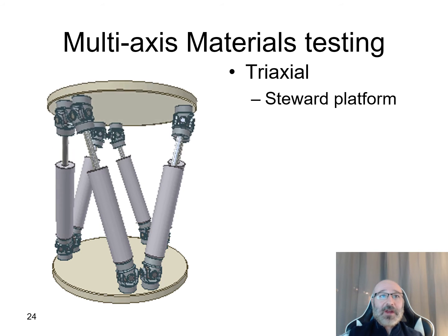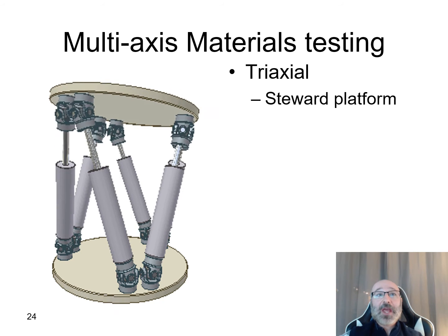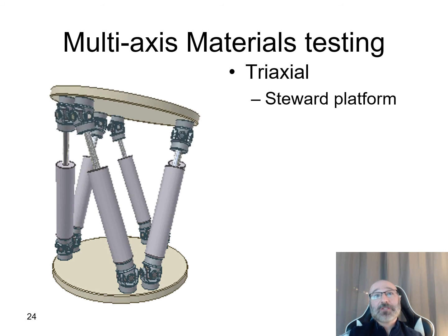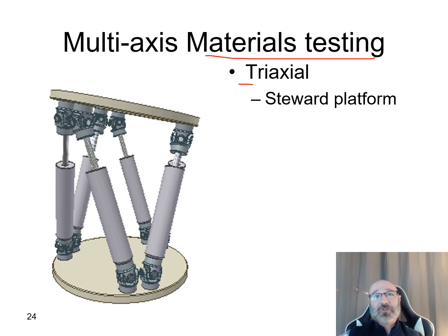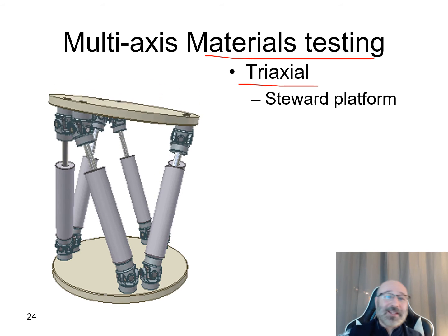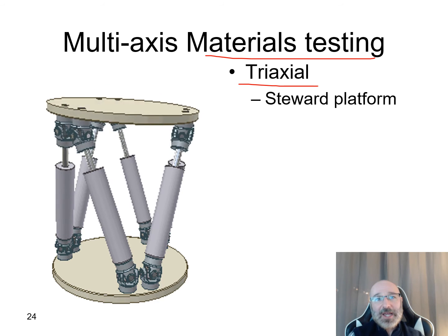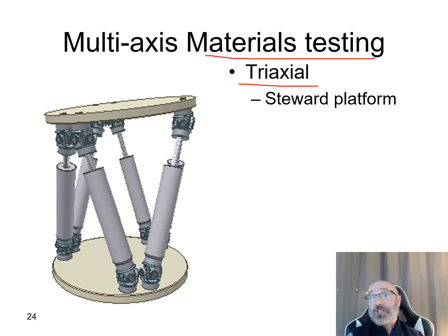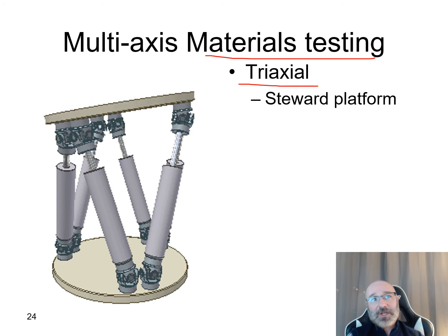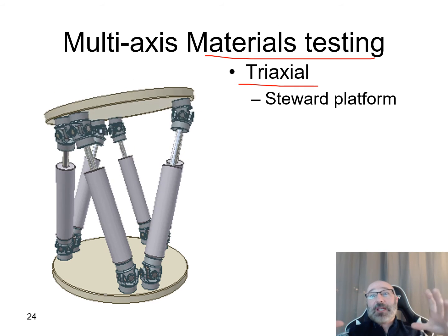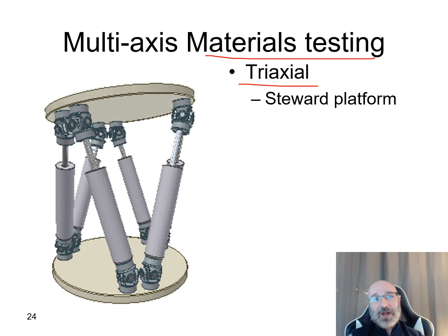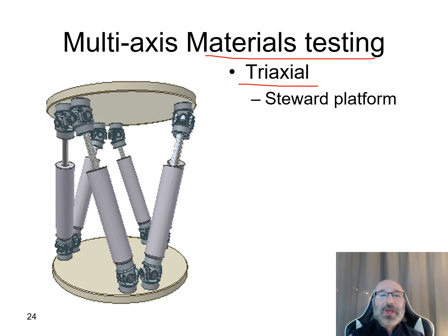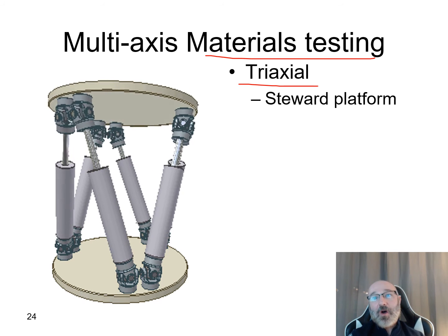And last, a very unique and special case, we have a multi-axis material testing machine. This is a triaxial one. And again, a lot of these are very, very custom designed. I was working with a company testing ratcheting medical tourniquets, and we needed an expansion in 360 degrees around to simulate a limb, to put it in tension all the way around the whole thing.